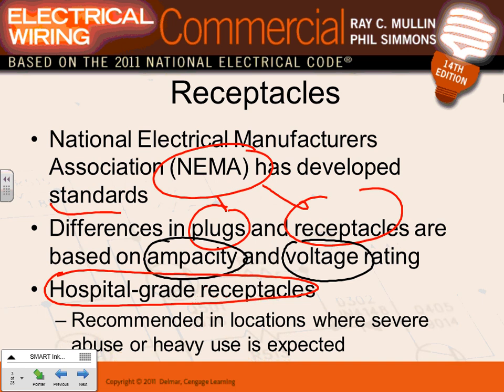Tamper resistant receptacles cost $1.30, and then there's a receptacle that costs you $5, $6. So what's the difference? Both of them look exactly the same. The receptacle that we use in residential is called a residential grade receptacle. They're cheap, they're manufactured cheaply, meant typically for residential.